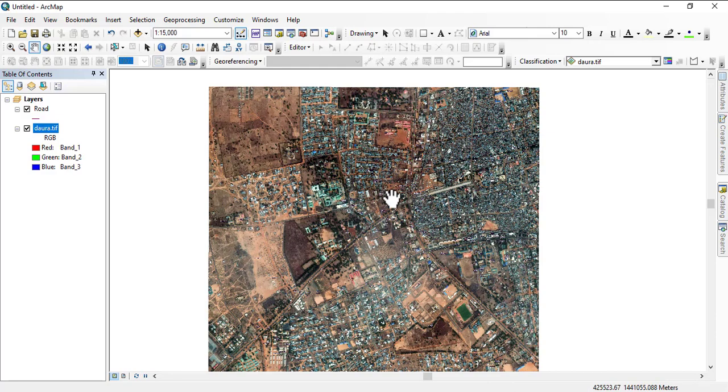And you will first need to digitize your expressway or your major road first, because those are the main network connections. Roads are not meant to be hanging. Roads are not meant to overshoot. Roads are meant to have a connection. So roads must be connected.